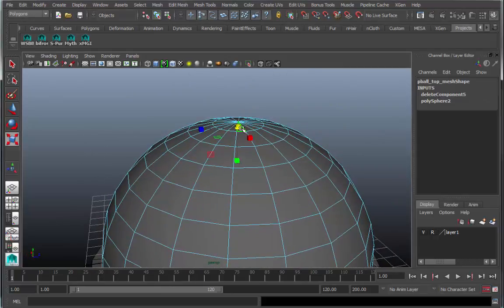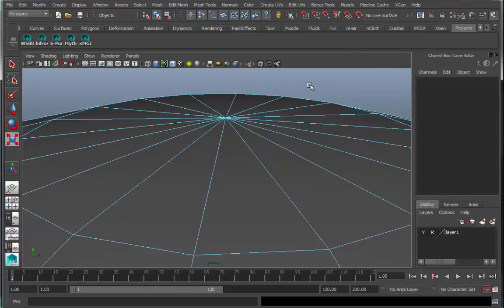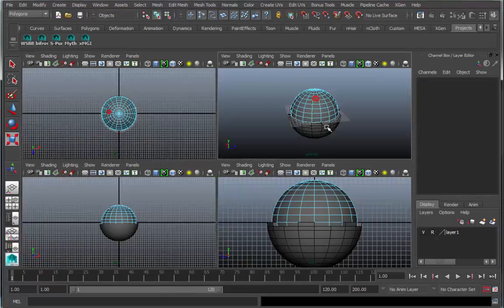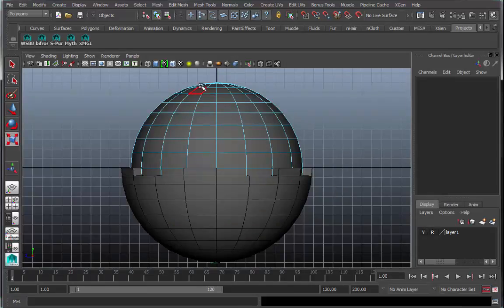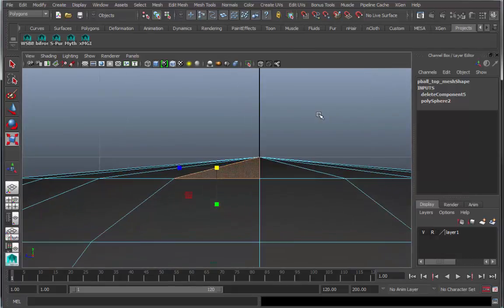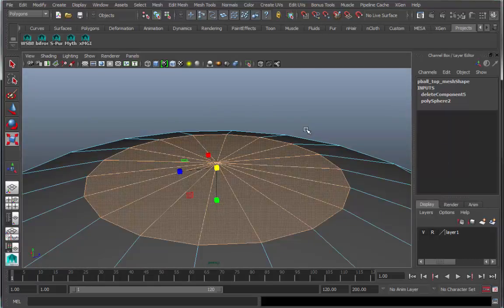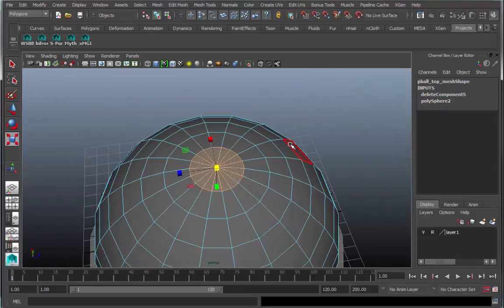So what you want to do is maybe grab one face, press F, come up here, shift, select each of these. That's fine, as long as you double check your work. But there's an easier way of doing it. If you take any of these orthographic views and select the same single polygon, then press F, it'll do a close-up right in that area. And you can use your scroll wheel to get pretty up close and personal and select a very careful selection square around just that top part. Now when you press F, it's going to come in just on that selection ring.